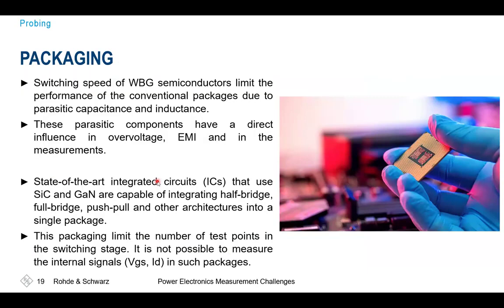As mentioned already, the packaging has a high impact today on what we are seeing there. We know these BGA, so ball grid array packages, from semiconductor devices for quite a while. In the range of computing, system on chips, and so forth, these no longer have any footprints like a TO package or something like that. You'll always have these ball grid arrays.